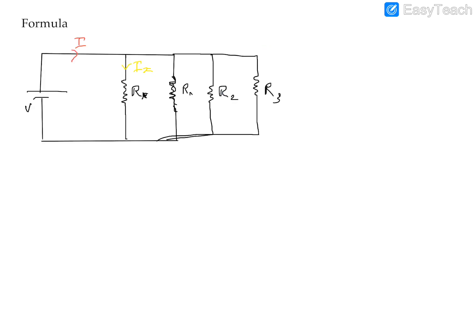Okay, so here I have a circuit drawn out already. I'm going to write this up a little bit more clearly. This is going to be Rx, this is R1, R2, and R3. So this circuit has four branches containing resistances Rx, R1, R2, and R3. And I am very much interested in the current that's flowing through Rx. Since I'm not interested in the other branches, I can just group these and write my circuit somewhat like this.